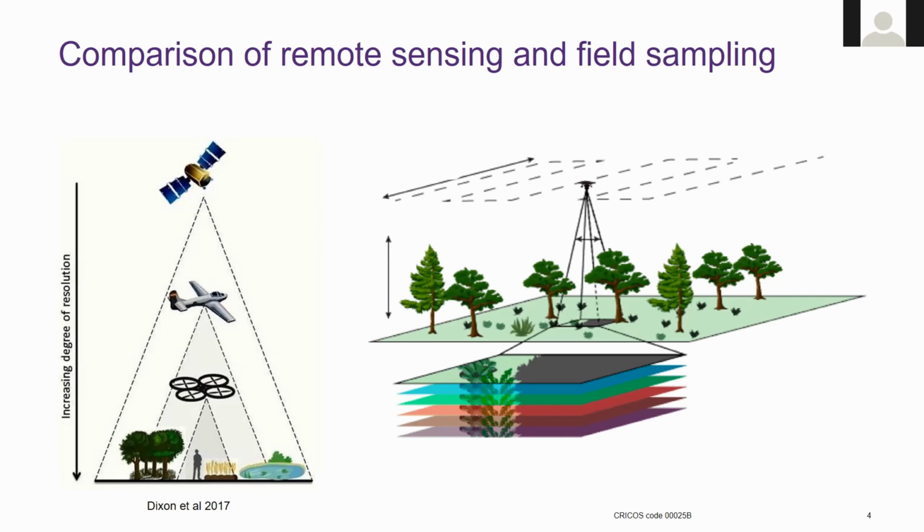So we're talking 90% overlap between each individual photo. That allows you to build quite complex and detailed, 1 to 2 centimeter digital surface models. And that image also demonstrates that, depending on what sensor you're flying, you can have multiple and specific wavelengths collected.